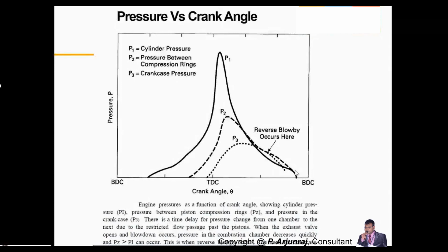When the crankcase pressure goes up, it gives additional load to your cylinder block, basically your combustion chamber. It will create some additional pressure build-up and it will create some problems, because unnecessarily we're creating an additional thermal load.